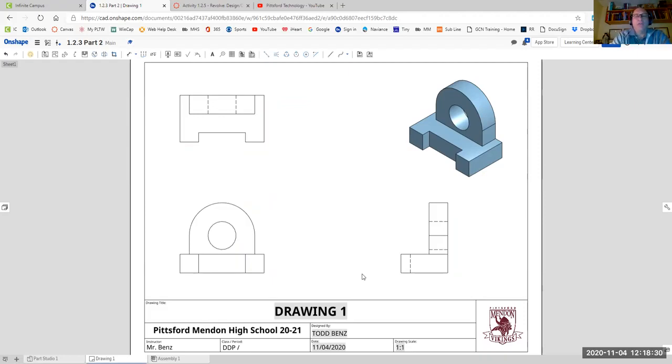So you can see that I have a circle or an arc. The next thing I want to do is go up on the top. You'll see a little round circle with an X through it. That's called center mark. I'm going to select that. I'm going to select the outside edge of my circle or my arc, either one. These both happen to share the same center point. They're concentric, so I'll only see one of them in there. Now I want to put my center lines in.